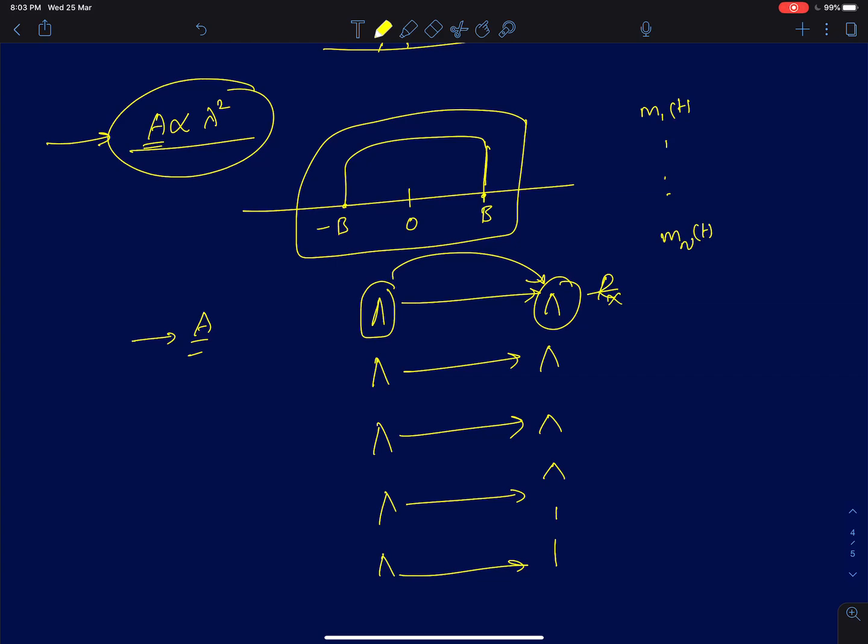The obvious answer, of course, is that the area of the antenna is no longer an issue. Yes, you can. That is using a principle called time division multiplexing. So what we will do is, there are n users, n of them want to communicate. There will be a central clock, a master system, which will tell you, let's assume they're all communicating for 100 seconds. I'll give 10 seconds for the first guy, 10 seconds for the second guy, 10 seconds for the third guy, and so on till the 10th guy gets the 10 seconds in the 10th slot. So this way he can transmit the data.